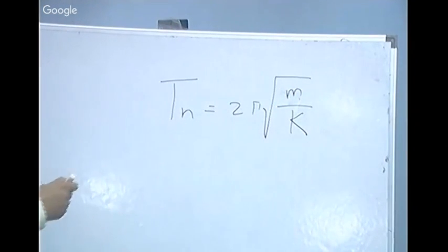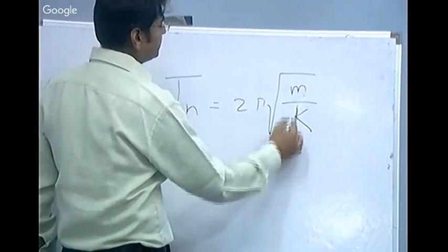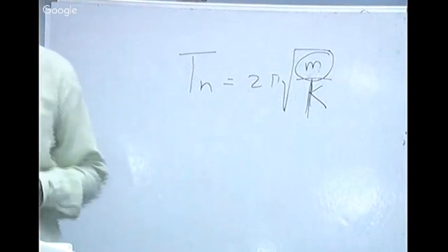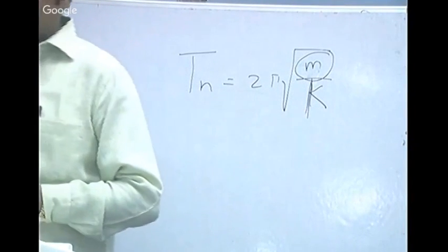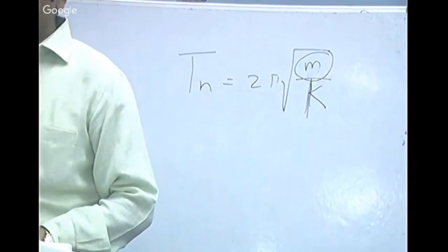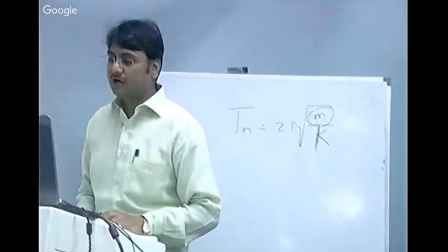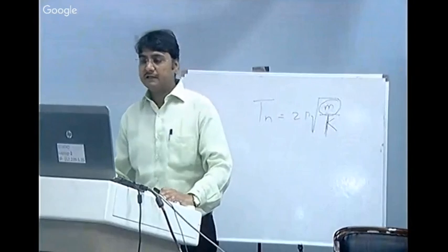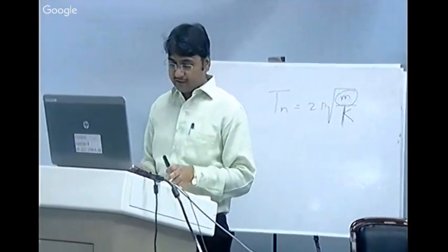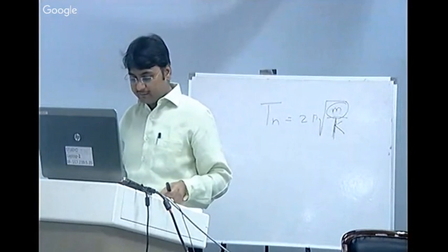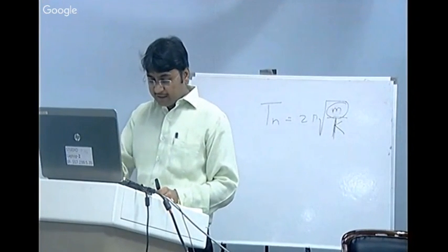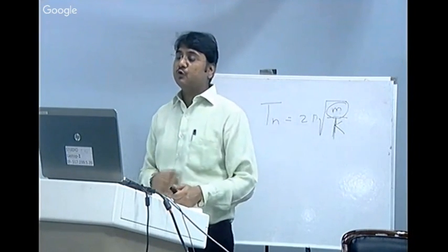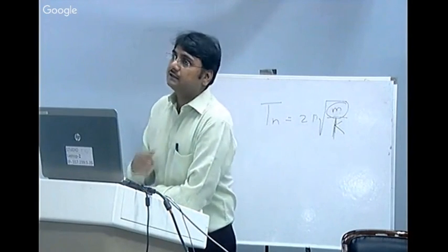Here, we cannot change the stiffness of the building, but engineers can reduce the mass. How can they reduce the mass? They can choose simple lightweight materials or lightweight roofs to reduce the mass of the structure. If we reduce the mass of the structure, then the fundamental time period will be less. In taller buildings, the fundamental time period is more.